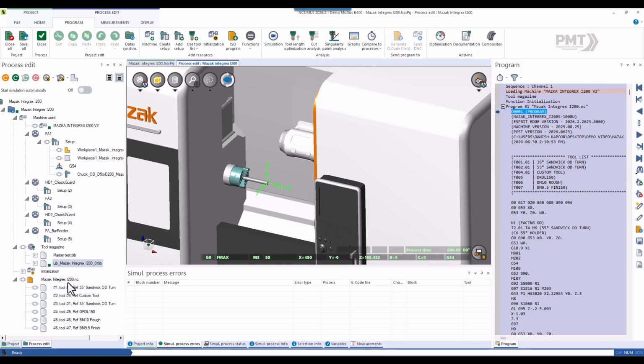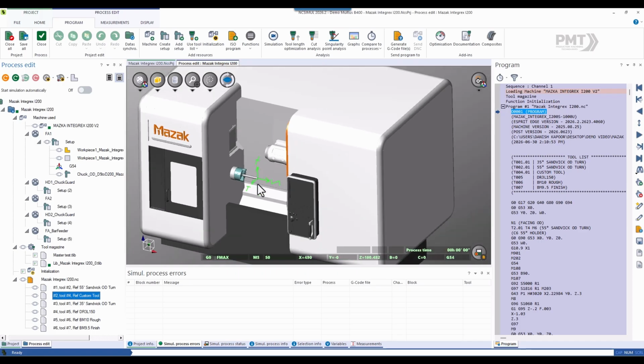And then this is the NC program that we posted, right? So it automatically breaks it down into different tool sequences so we can start our simulation from that point. And also, if a change is made to the same NC program, you don't have to run the simulation again. It saves the rest stock material up to the point of change. And once it finds that there is a change, it will ask you to rerun the simulation from that point on. All right, so enough of the talking.